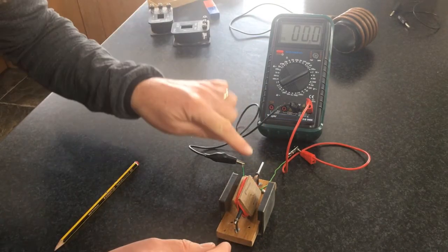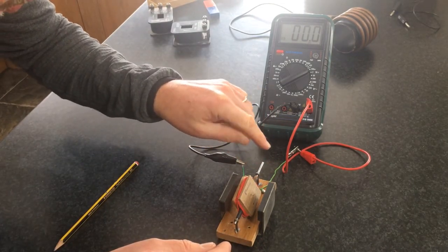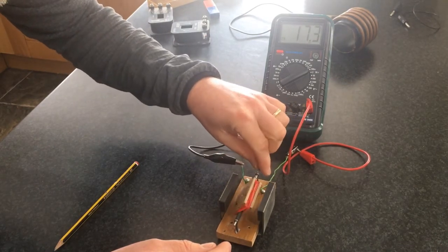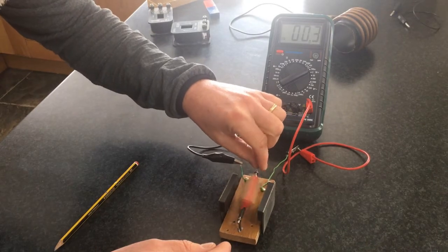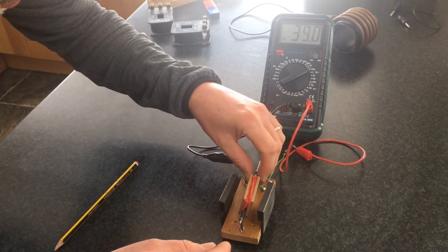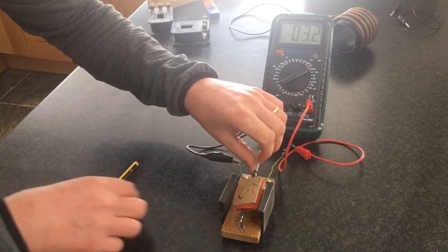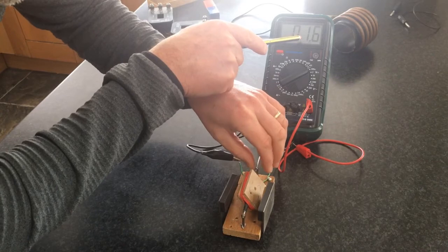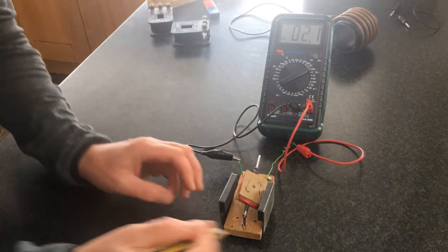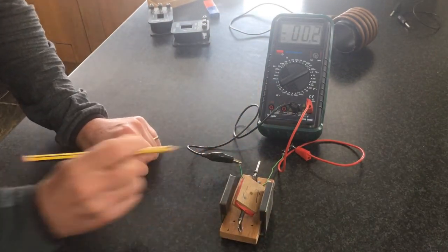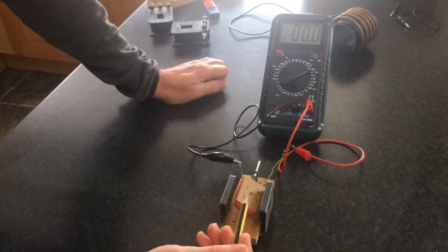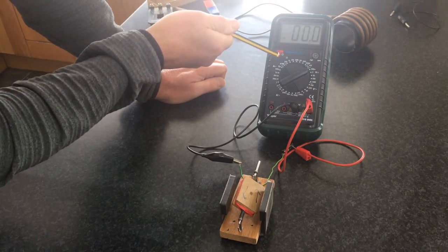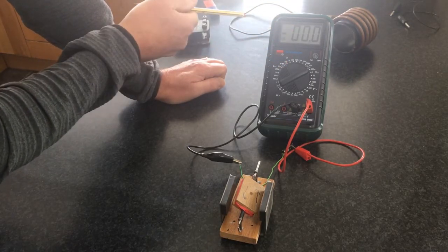If you imagine now that this spindle was connected to a wind turbine, and the wind turbine is rotating, let's make sure my connections are touching, you can see as it's rotating, it's generating a potential difference there. Not much, but a potential difference. Because the connections are swapping every half turn, even though this is rotating, we end up with a direct voltage, which will give you a direct current.